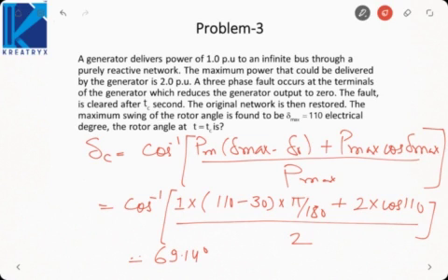Okay. So that is your clearing angle. Though it is not the critical clearing angle. For critical clearing, you have to keep delta max equal to 150 degree. So whatever formula we have seen for tcr and delta cr can be applied for delta c, which is any clearing angle, and tc, which is the clearing time, though they may not be the critical values.